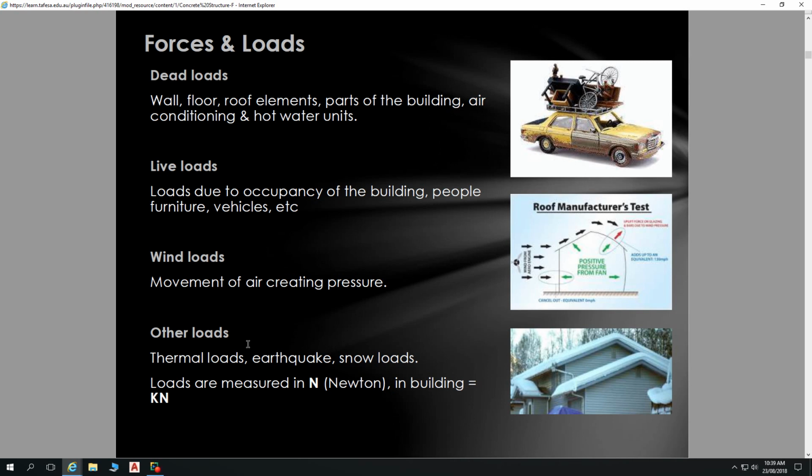Whereas if it's brickwork and you get some damage to a section, it's not as involved. But certainly there are trade-offs, and that is the way that building is going in general: to get stuff off-site where it's dirty, messy, in the weather, and in an uncontrolled environment where people aren't observed as closely, and get that happening in factories where it's all controlled, where you can have efficient use of materials, get elements built there, and get them onto site. So certainly what you're talking about there is the general progression of things.